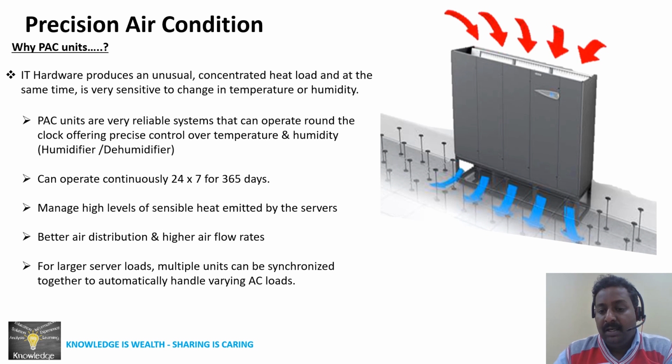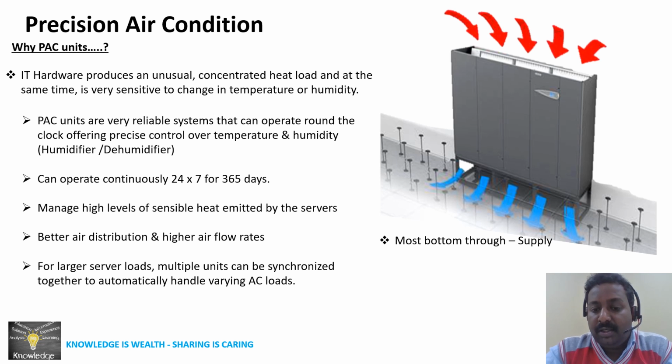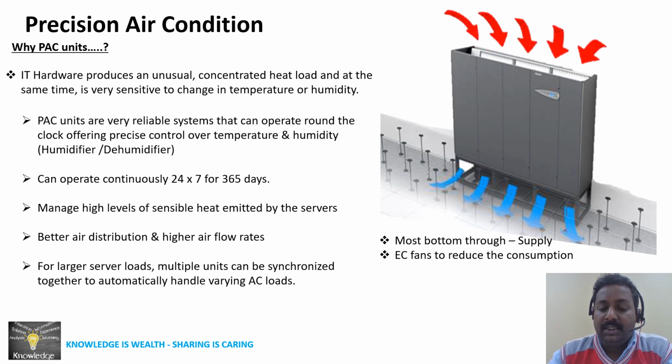Another few points: most of our PAC units are bottom throw, because most of our labs or data centers have raised floors, where we plan supply air bottom throw. A PAC with top throw is also available. We rarely see it, but most of our PAC units are bottom throw supply. And nowadays all PAC units are coming with EC fans to optimize energy consumption. And I already told you it has a smart control system